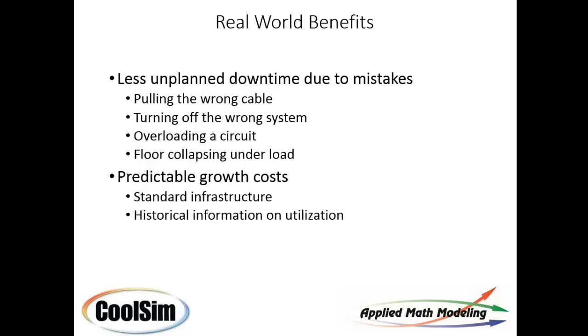I actually had that when I was at Vanderbilt. We had a really old data center that had a floor in it that was put in back in the 70s, and just over time, the wear and tear of rolling these loads over a tile decreases the strength of that tile.